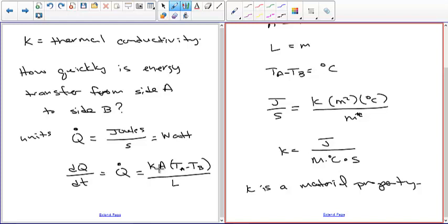The other thing is you put a fan in it. If you blow air over those fins, you're doing a different kind of heat transfer. Instead of conduction, it's called convection. By blowing the air over the fins, you're taking the hot air molecules right at the fin surface and replacing them with cooler air.